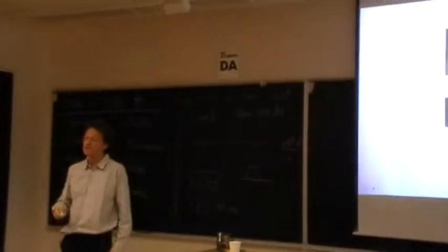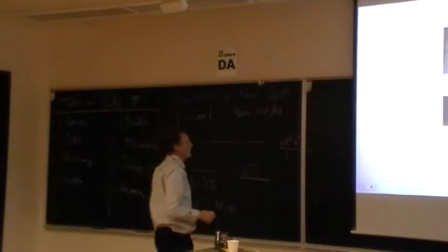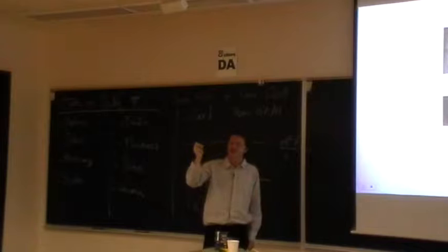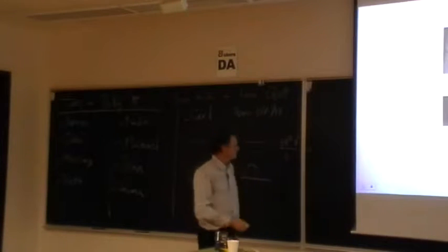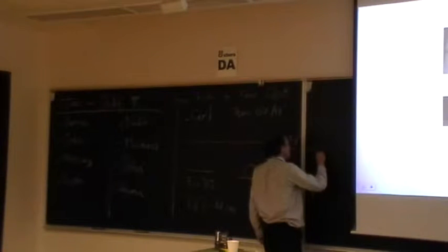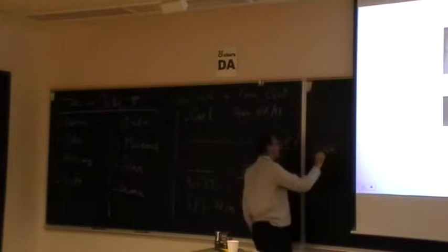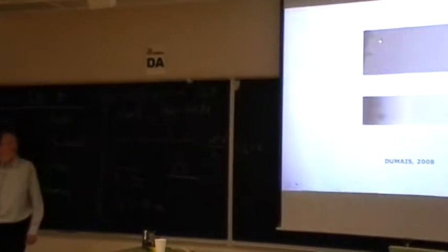Here I wrote the inertial force, and L is my unknown. This force is balanced by a viscous force, because you are at a very small scale, the velocity is not that high, and so the Stokes force is dominant. So you expect a force which is just viscosity of air, velocity times the size of the spore.